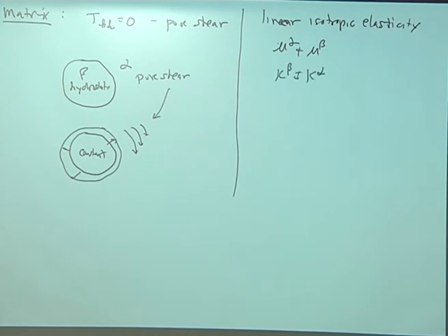So in other words, there could be differences in elastic constants, and we've assumed all of this, and we get these interesting results that the stress is hydrostatic, it's constant. It turns out that this also holds for ellipsoids.